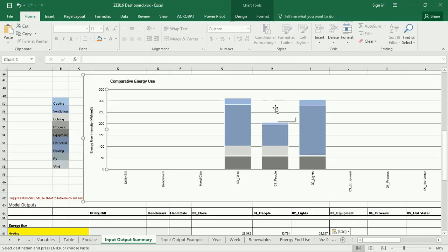So you can see in this that the model is very sensitive to ventilation because of the people, occupancy patterns. And if we can control ventilation, then we can have a better shot at reducing the energy in the long run. You can also see the model is relatively sensitive to lighting energy, which also gives a hint that heating is really important, because right now we're using the lights to heat the building. So if we could have a more efficient heating system, and maybe more efficient lighting system, we could dramatically impact the overall energy use.